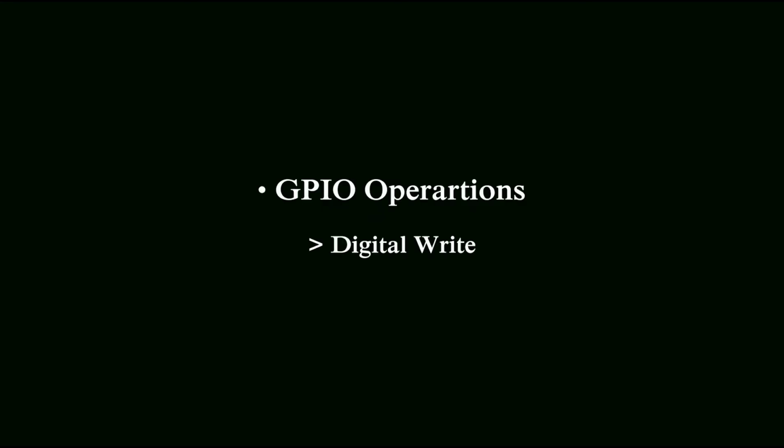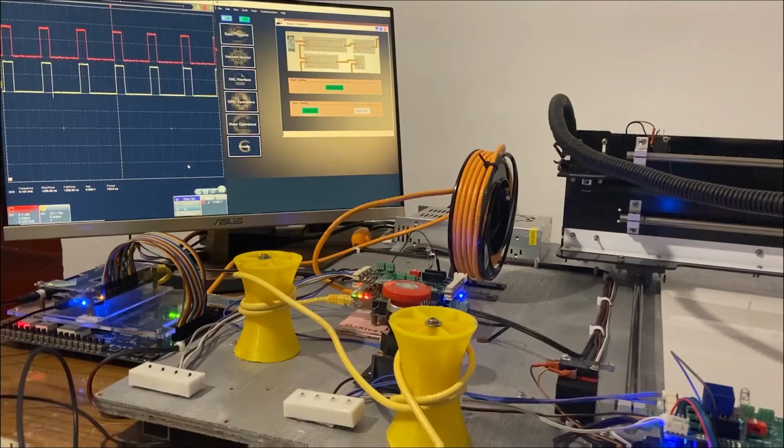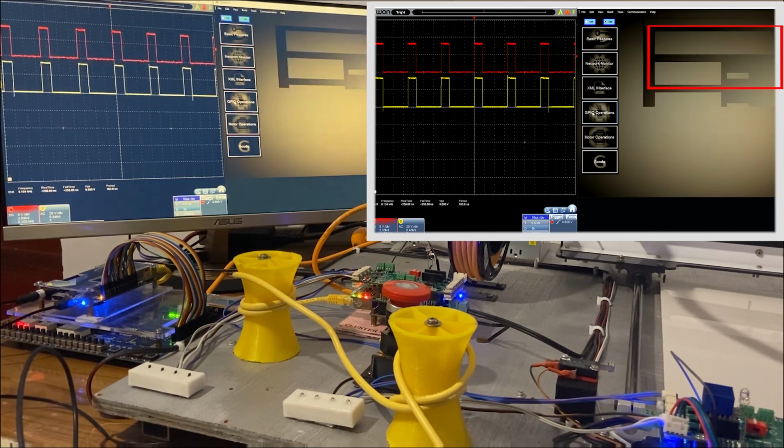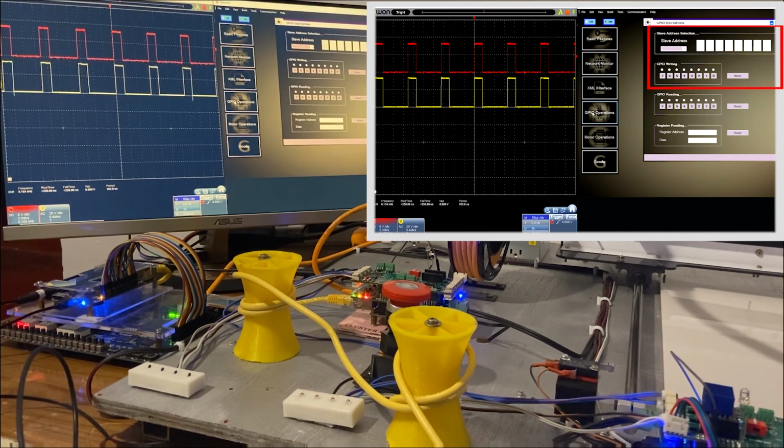Digital write scenario can be demonstrated by writing a specific pattern to a specific slave. Once done, the pattern will be visible in the relevant slave's LED panel. Here we have chosen slave 6, since our LED panel is connected to the first 4 output pins of it.